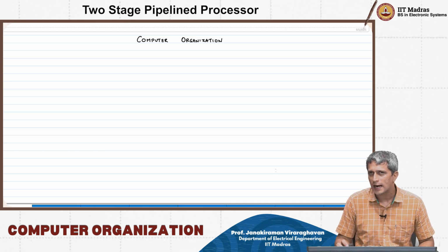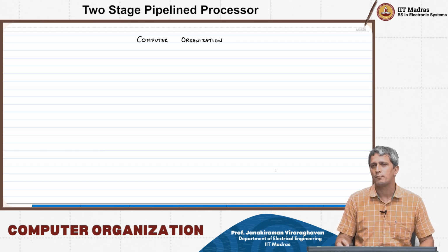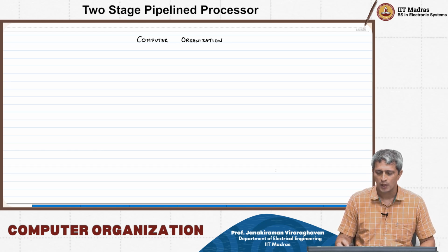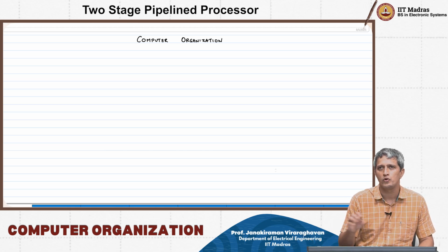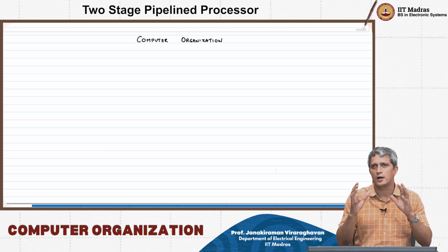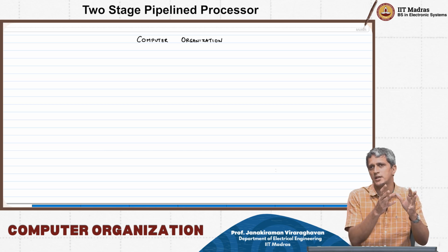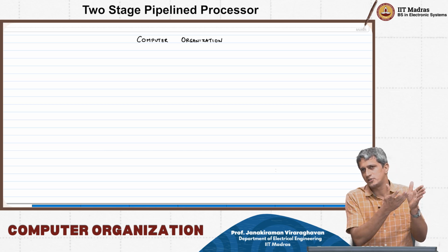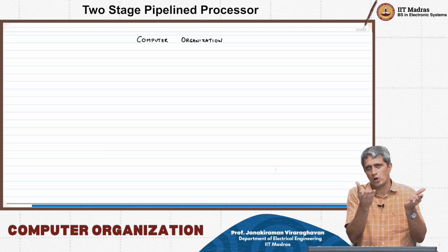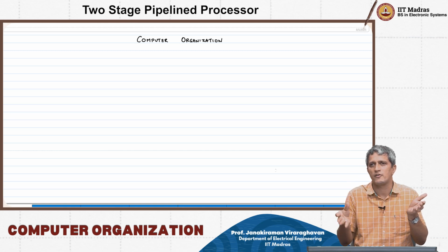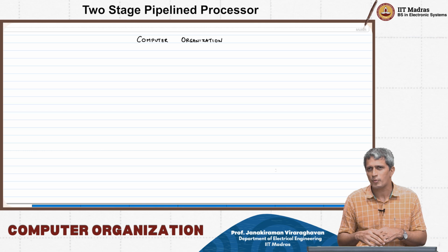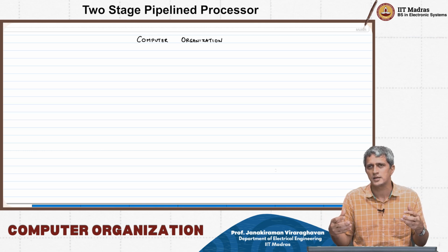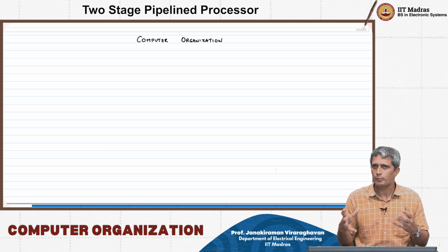So having looked at the 5-stage pipeline processor construction and also having just looked at the control unit very briefly, we just said that the control unit is the same as that of the single cycle processor. Control signals generated just flow through flip-flops and then drop off wherever necessary. So this was stated in a very simple manner, but it's also good for us to understand the flow of these control signals and the data through a pipeline processor.